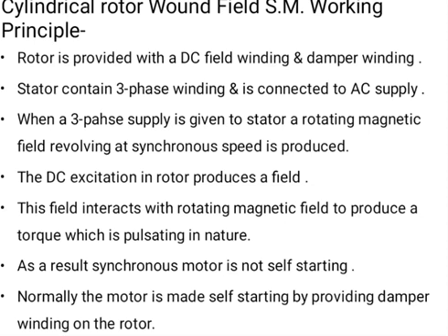Now we will discuss the working principle of the cylindrical rotor wound field synchronous motor. The rotor is provided with a DC field winding and damper winding. The stator contains a three-phase winding and it is connected to the AC supply. When a three-phase AC supply is given to the stator, a rotating magnetic field revolving at synchronous speed is produced, and the DC excitation in the rotor produces a field.